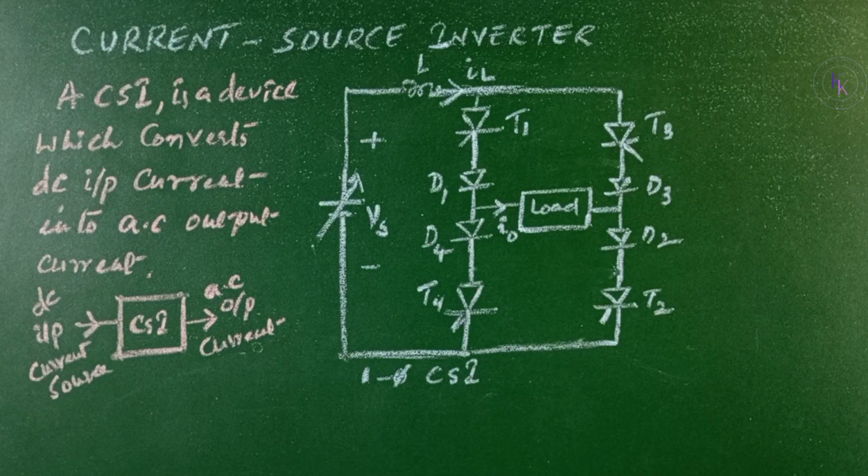The advantages of current source inverters are, first, as the input DC current is controlled and limited, misfiring of switching devices or a short circuit would not be a serious problem. Second, the peak current of the power devices is limited inside the inverter. Third, the commutation circuits for thyristors are very simple. And fourth, it has the ability to handle reactive or regenerative load without freewheeling diodes.